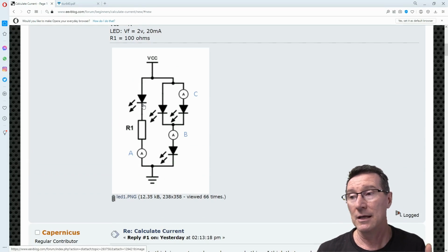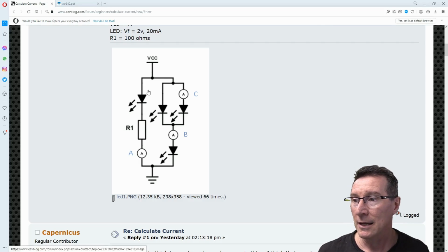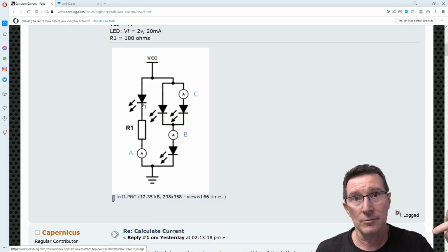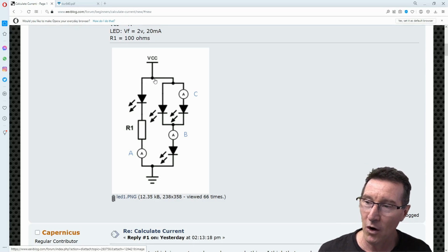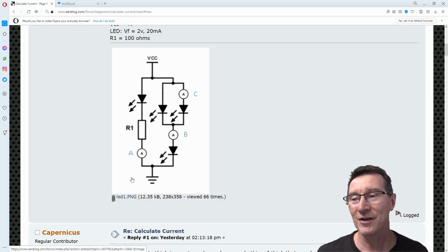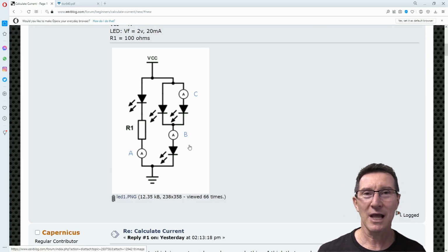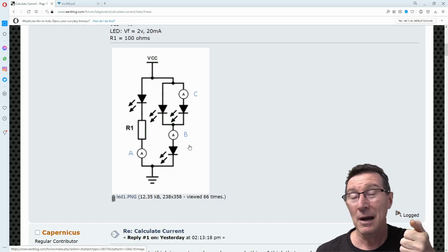And of course, the brightness is not a function of the voltage, it's a function of the current. Diodes, including LEDs, light emitting diode, it's in the name, are essentially current-driven devices. The voltage drop happens to be a result of driving it at a particular current, but they're not voltage-driven devices. That's not their intention, which is why it's stupid to not have a current limiting resistor or some sort of constant current circuit driving an LED. Don't do it. But then there's people who say, oh, those little keychain flasher things, they put the LED directly across the battery. Well, batteries have internal resistance, so you do effectively have a series resistance in there.